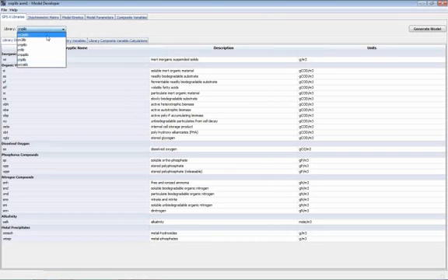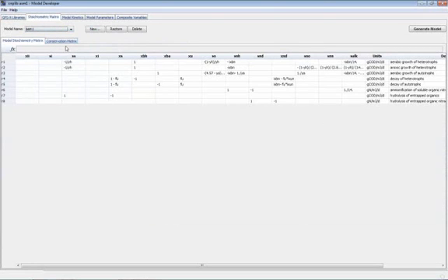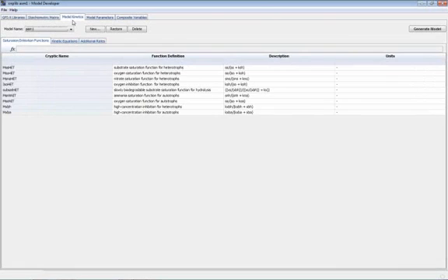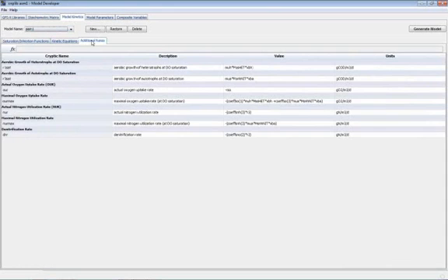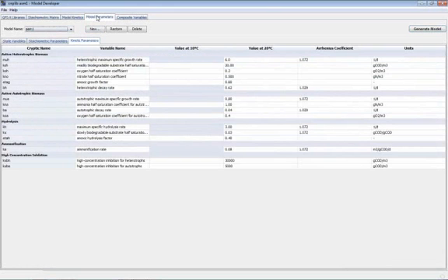And you can see, first of all, you can pick from the libraries that are available. You can then go to different stoichiometric matrices here by selecting amongst the ones that are available. You can see ASM1, 2D, and so on that are here, plus a few other ones that I've been working on for various projects here recently. And once that's done, you can now enter in new stoichiometry. You can create new rows and columns in the stoichiometric matrix here. You can add new saturation and inhibition terms and any other types of additional rate equations that you would like. And, of course, all the model parameters. So that's automatically listed here.